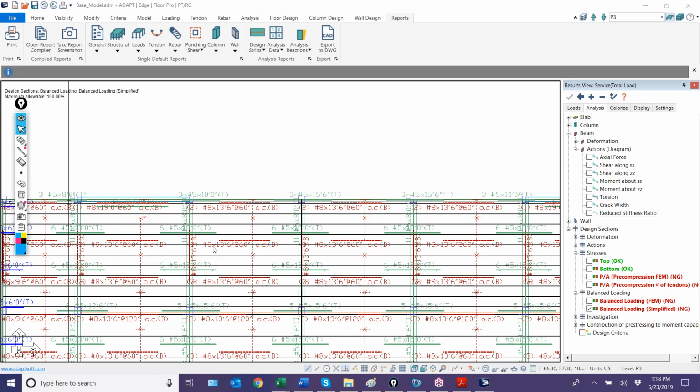Either you use the full flange, in which case we would anchor the tendon at the CG of the full flange, or you introduce design splitters, let's say, and model your effective flange, and then you would have to adjust the CG relative to the effective width of the beam.